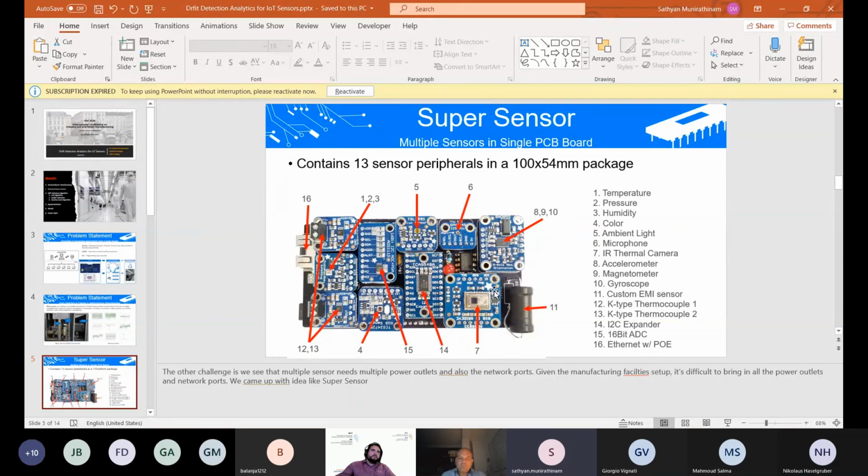And then we do some of the manipulations within the device itself, right? If you look at the hardware configuration of the ODroid, that itself is a pretty beefy server. We have 4 cores, and we have an NVIDIA GPU running within the ODroid itself, right? What we want to do is more edge analytics there. I didn't put it here, but I'm happy to share a little more detail on what we did in this specific one. The two things, right? Obviously the compression and also the binary format of the data that we want to transport from the edge to what we call the fog, or the middle server, the central server for more processing.